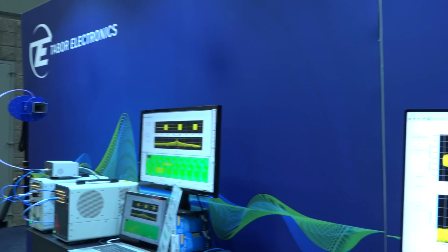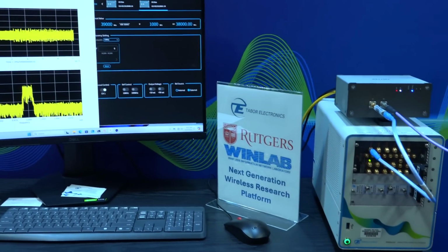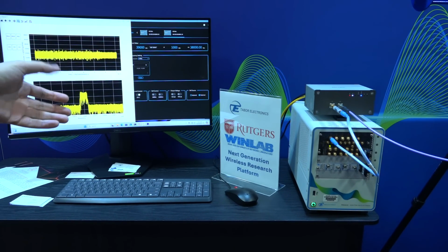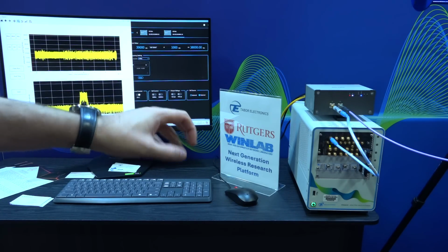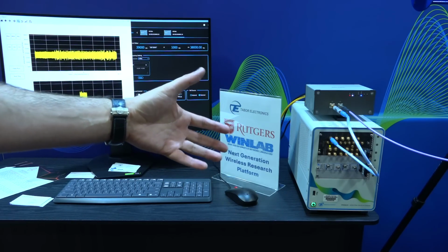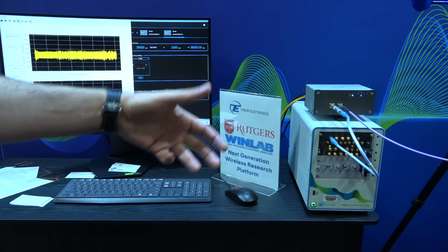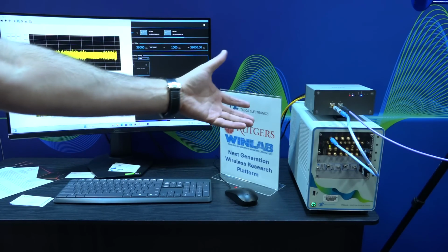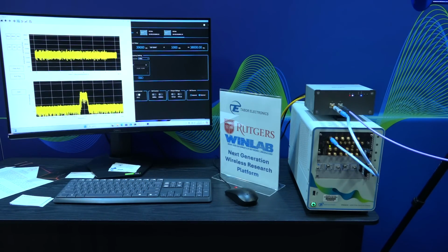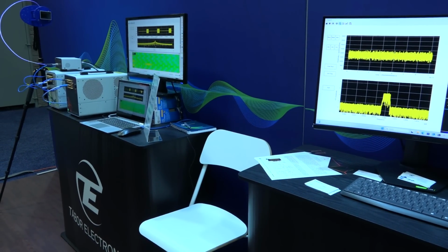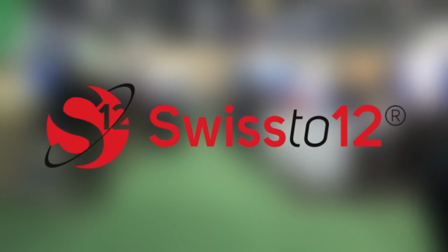Because you have full control over the API and you can run your own script and write your own code, you can generate any waveform you want. You can combine them and analyze them and figure out how you can de-embed them from each other. It becomes a platform, not just in terms of the millimeter wave capabilities itself, but also in terms of signal processing and how you code things and decode them and how you would deploy them in the field. And you can mix and match them with essentially anybody because it's almost open in that sense. So this is becoming more and more of a powerful platform for future research as well as practical industrial applications.